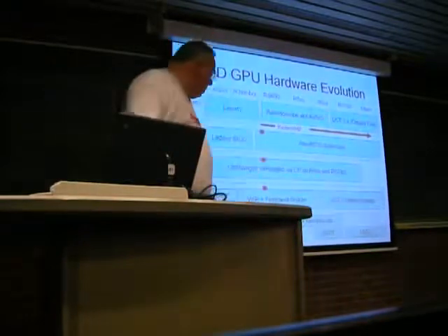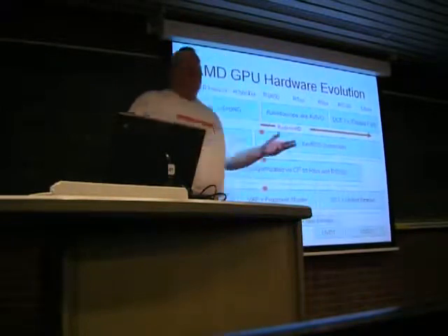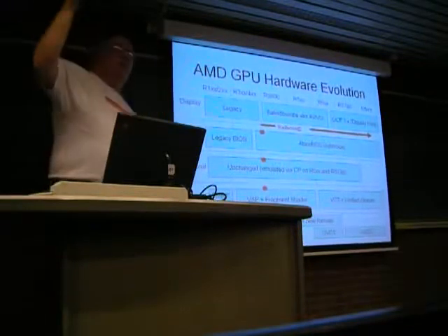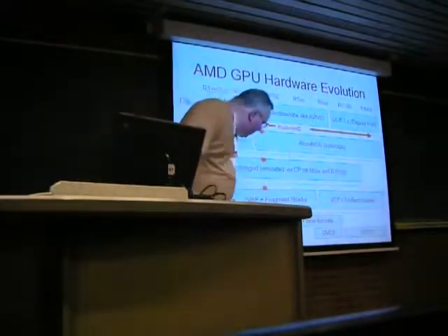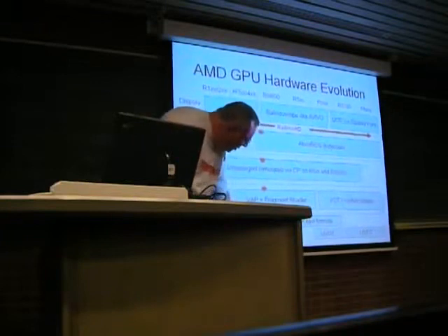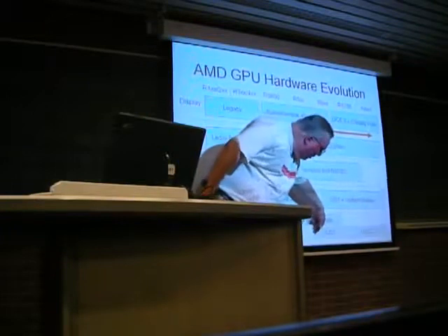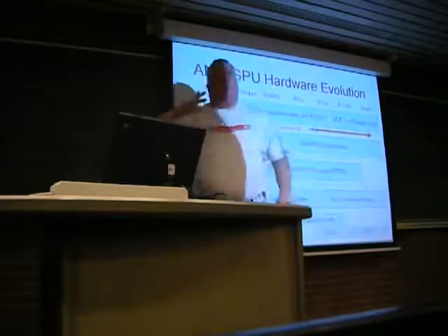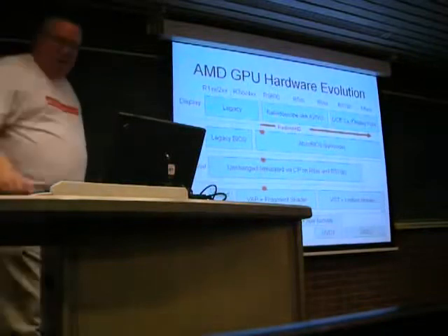It's looking like we should be able to open up the information on this. Motion comp is really the 3D engine with some specialized mode, because MPEG has some different requirements, everything from rounding and those kinds of things. So fundamentally, render processing and motion comp are all 3D anyways. The IDCT and the newer ones for H.264 and VC-1 are handled in UVD. We're not sure about opening up the UVD block yet. We're going to try, but right now I don't have a way to do that.